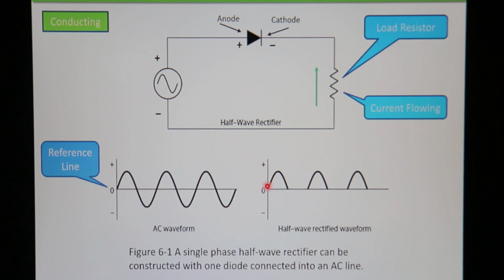If we come over here, I have all my voltages above the 0 volt line, nothing crosses it, then this is DC voltage. I could also have these three pulses on the bottom. It'd just be negative voltage. Never goes to the plus side, it would be DC voltage. Okay? And that's really the difference between AC and DC. It's all in relation to the reference line. So if you'll just always remember looking at that, you should be fine.